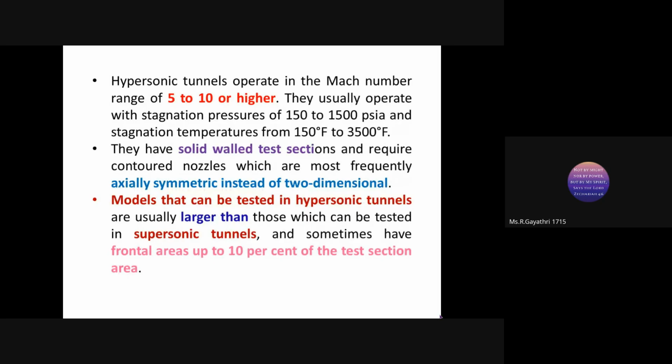For supersonic case, we can keep even 1 atmospheric pressure, but for this hypersonic, we can't proceed with this lower value. We can aim for higher values. Ranges from 150 to 1500 psia and stagnation temperatures from 150 degree Fahrenheit to 3500 degree Fahrenheit.